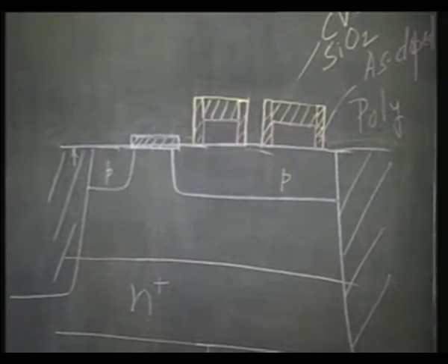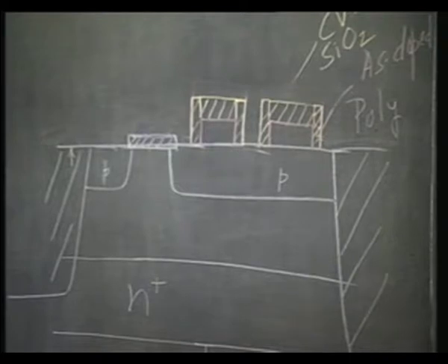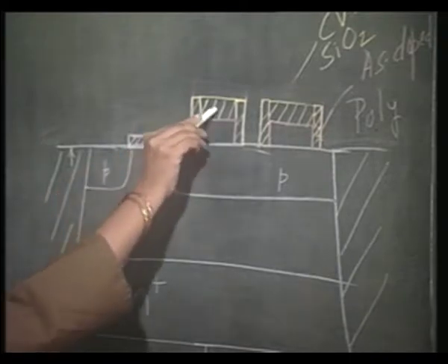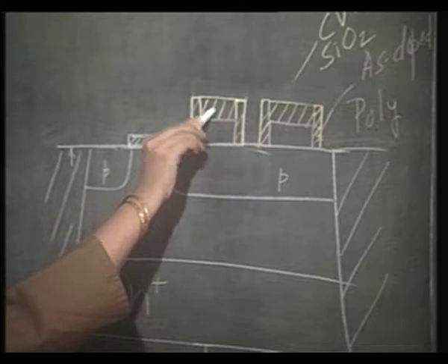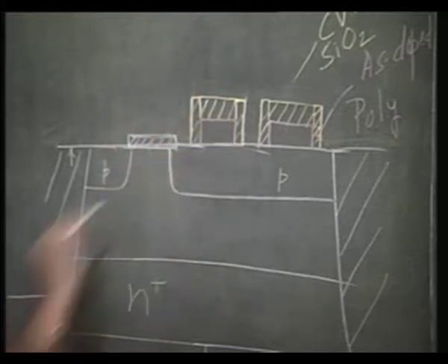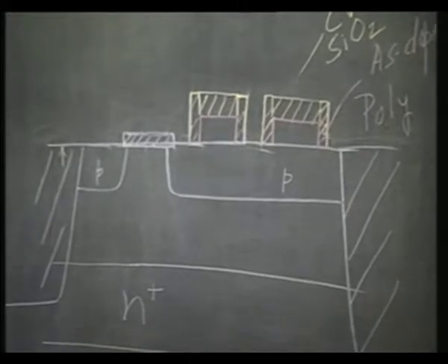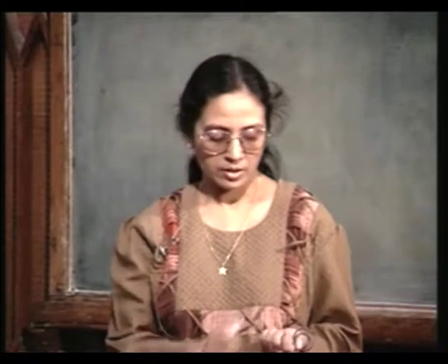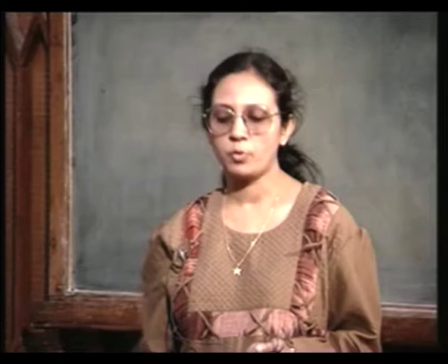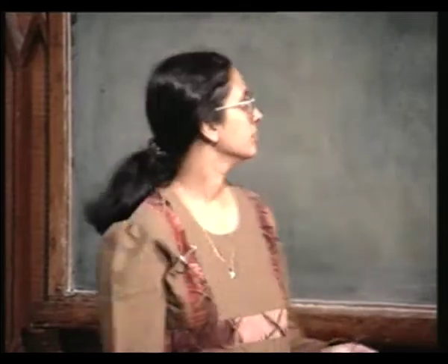So you see now, in addition to having the top capping layer of CVD SiO2, I have also added a side wall of CVD SiO2 to my N plus poly regions. Agreed? Now all I have to do is to deposit the metal, aluminium.